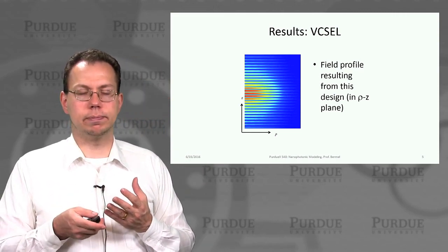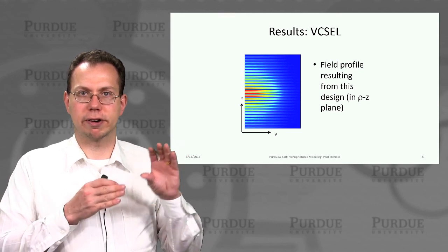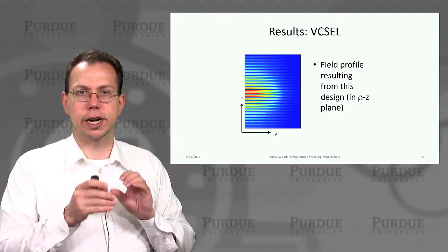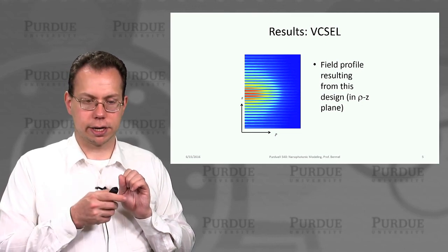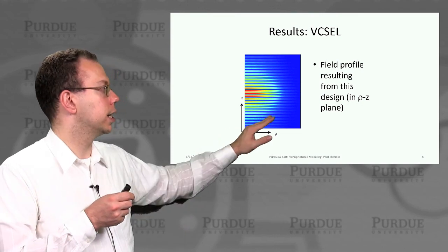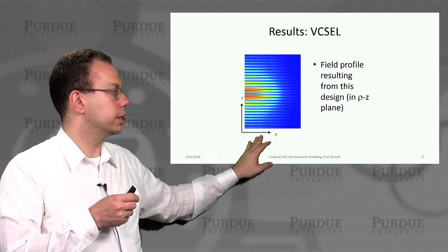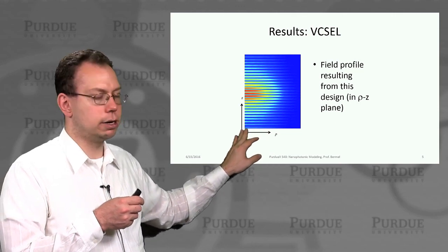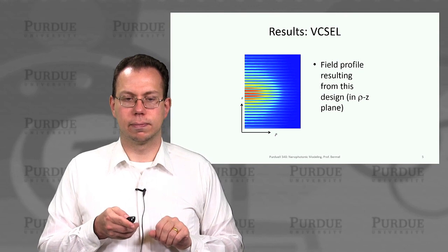It's localized, of course, in the vertical direction by the distributed Bragg reflectors, but in the radial direction by the high refractive index waveguiding effect. And so this allows you to selectively emit only in the vertical direction, particularly if you put a back reflector, say made out of metal, on the bottom of the system.